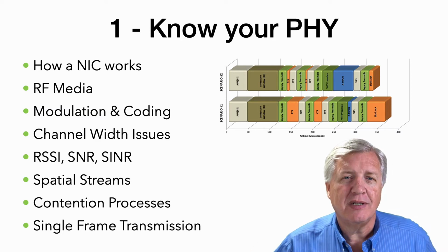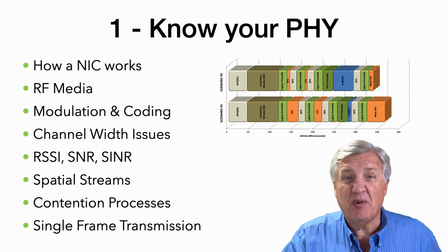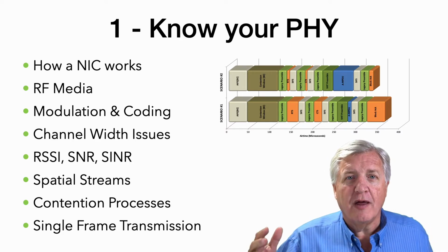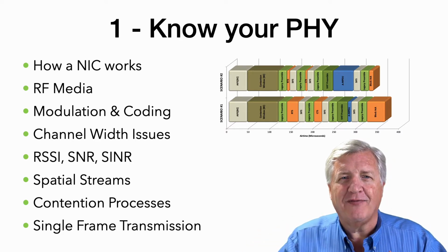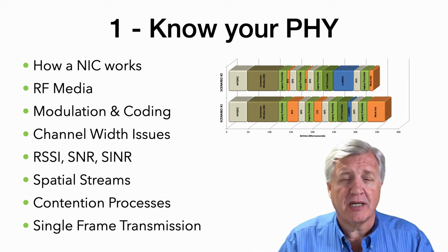Co-channel interference? Wi-Fi 802.11 is 100 times more sensitive to other Wi-Fi than to non-Wi-Fi. It's built right into the protocol. So don't ignore the fact that Wi-Fi is the number one enemy of other Wi-Fi. It's going to have to come into your design process.